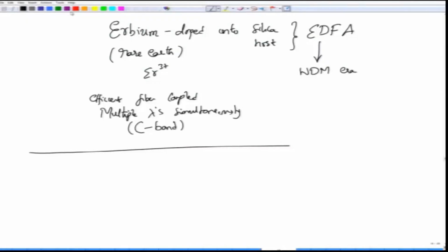If you recall what the stimulated and spontaneous emissions were, you had materials which had certain energy levels. So, let us say this material had an energy level E1, an energy level E2 and an energy level E3. I am showing 3 energy levels because that is what is typically found in an erbium doped fiber. So, of these energy levels, you want to pick 2 and create a population inversion. This, of course, being the ground state, will be the first natural part of the 2 level system, and we have to choose between E2 and E3.